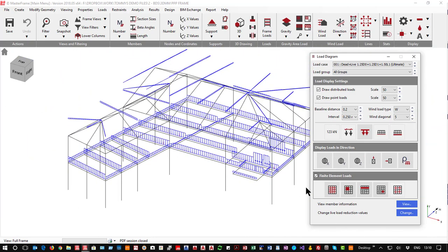You also control your finite element loads and what global axes of load. So your X, Y, Z, your normal to member loading, as in the wind loading, your normal to the binary axis, and also the good old-fashioned density, rho for density, if you're just wondering. So that's your dialogue, and I'm just going to close that.